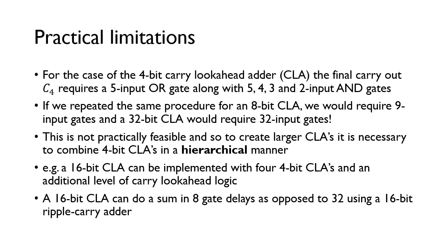So there are practical limitations to this. If we follow the logic through for an 8-bit carry lookahead adder, for example, we'd see that we need a 9 input gate, and then for a 32-bit adder we'd require 32 input gates. Now it's just not practically feasible to manufacture logic gates with so many inputs, and so the approach for creating larger carry lookahead adders, we normally combine together 4-bit carry lookahead adders in a hierarchical manner.